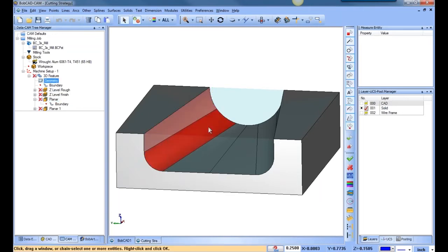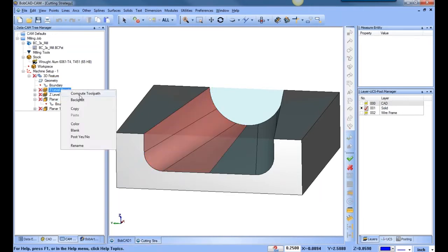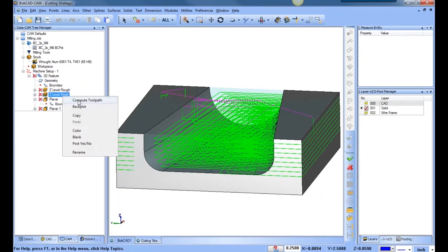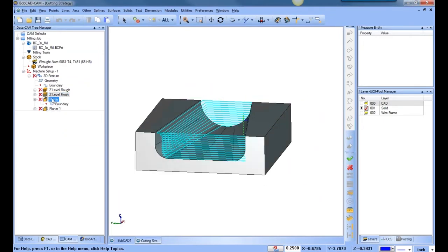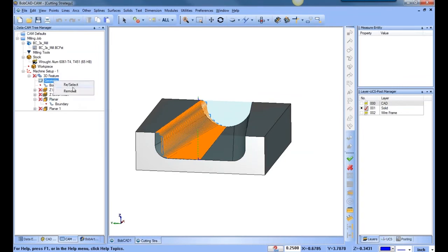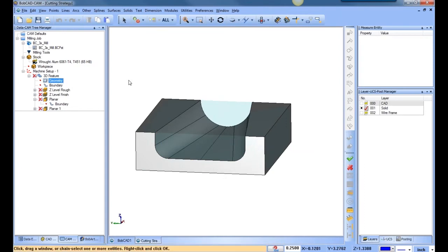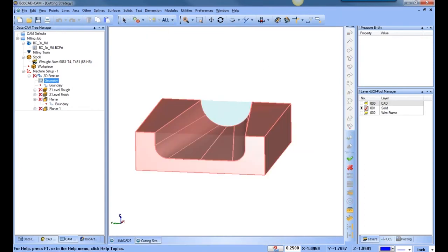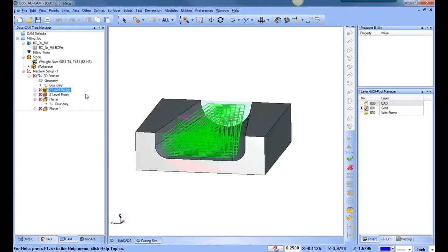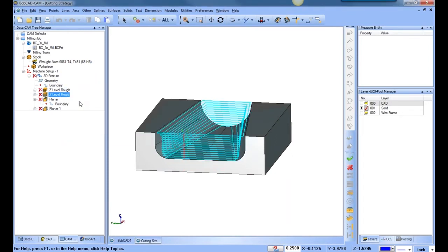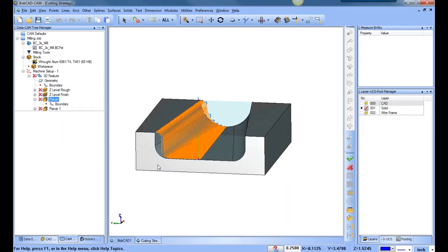If we go ahead and select some additional surfaces and recompute, again, what we're expecting to see is that we have an understanding of why we're getting that toolpath and why it's there. A lot of times for new users, what I recommend when you're selecting is to just select everything, because only the surfaces that you select are considered with the gouge protection and with the toolpath. So you're going to get a more consistent result with your toolpath when you've selected everything.